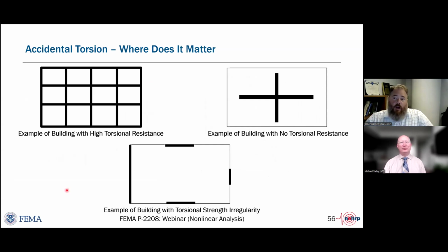So what we have done is artificially raised and lowered the mass over the plan that we assign to the nodes or to the elements in order to have the same amount of mass on the floor, but to have a center of mass that has been shifted the appropriate percentage from the center of mass if we uniformly distributed or distribute our loads as we believe they are distributed over the floor.